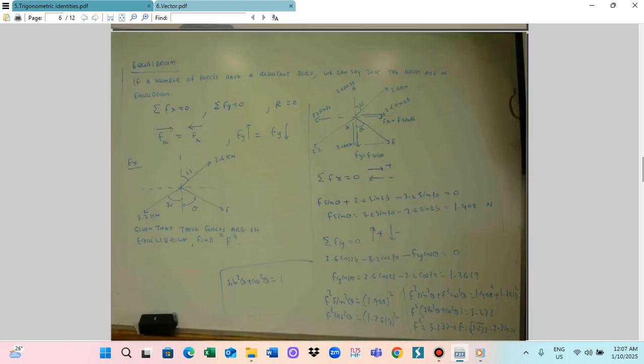So by this result we can calculate the FH and FY. So we resolve that when you see an arrow like this, at an angle like this, we have to resolve the forces into the horizontal and the vertical component. So F1 we resolve into F1x and F1y, F2 into F2x and F2y, and F3 into F3x and F3y. After that all the components are combined, and then use the Pythagorean rule and find the total resultant.